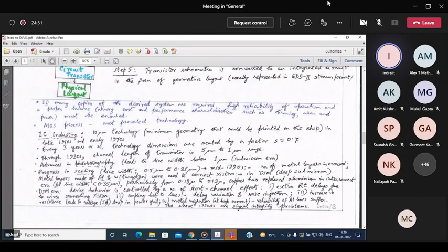On the downside, we have extra RC delays due to wires connecting transistors. RC delays cannot be prevented, and coupling between lines is also there. That means there can be a capacitive effect or inductive effect, and you have induced EMF, induced voltage. Due to these things, the delay can differ. Also, noise injection will be there. That means something undesired has been implanted in addition to the desired signal. Then an increase in resistance leads to IR drop and a drop in the power grid.